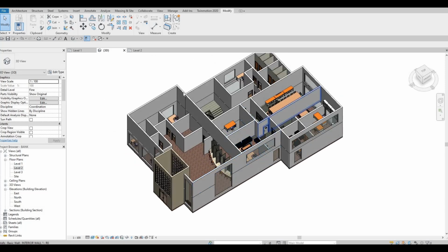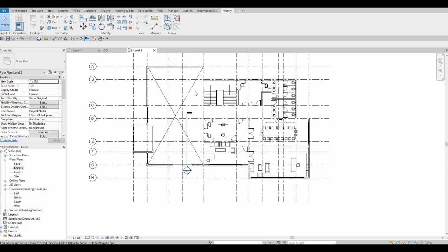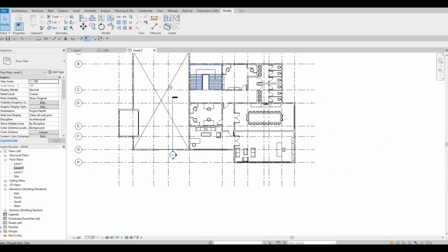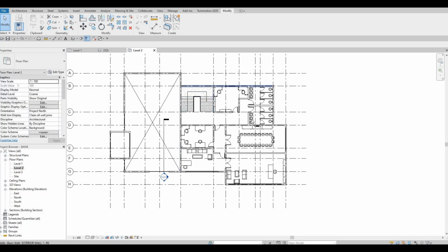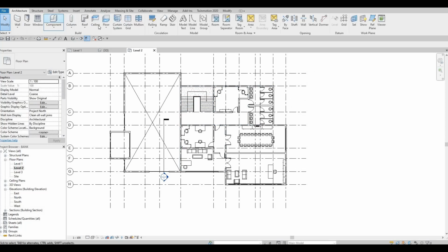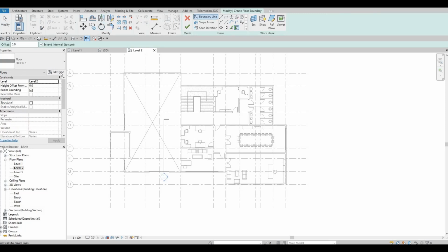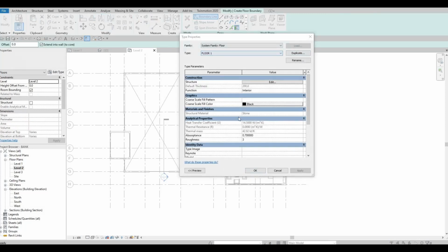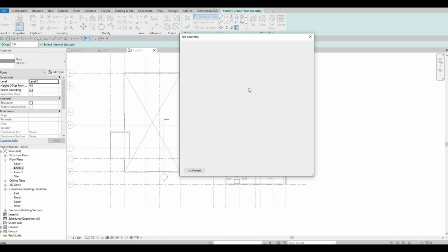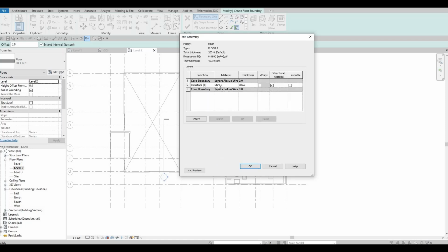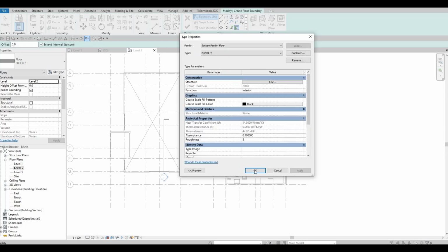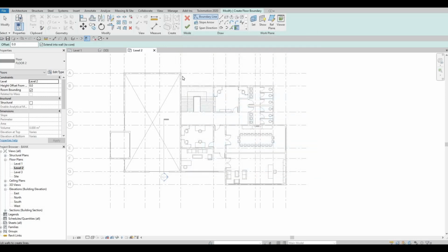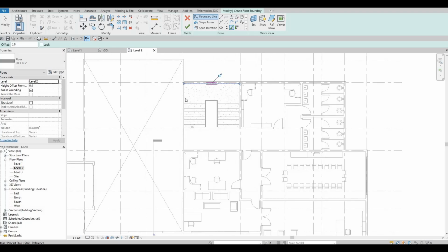I'm going to add floor for the second floor, and then we need to cover this off as well. Maybe we could set the same floor. So for now, let's focus on this one. Let's go to floor. Let's set this one to floor number 2. And then let's just add, make sure it's 200 again, and then let's put it at stone. And then here we need it from the inside.